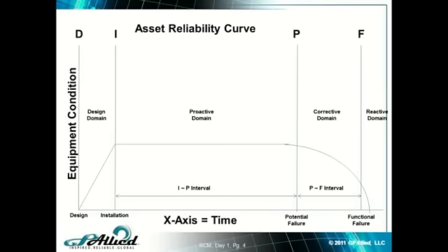Okay, reliability centered maintenance is a reliability tool, right? And what that does is it looks to develop or discover all failure modes, right? Predictive maintenance is a tool that's used to discover or detect potential failures or potential failure conditions, things like heat, noise, vibration, current faults, those types of things.